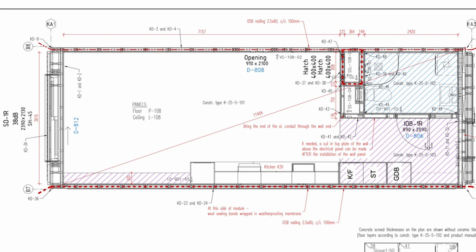Of course, in every technical drawing, it is essential to carry out the dimensions of the element. This plan shows all the dimensions needed to build this particular modular unit. Both the side dimensions and the diagonal of the module, as well as the dimensions of the location of the internal walls. Diagonal measurements are important to ensure that the module is square.